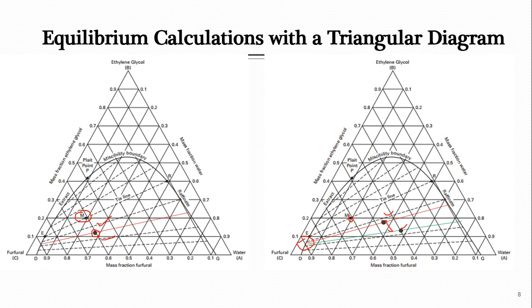So there will be very small difference in the composition, but on the raffinate side definitely there is a difference. You see here that by changing the position of this mixture point, the raffinate composition is changing from here to this, so there will be a difference in the composition. Due to this it is important to draw the line carefully so that you get close to the exact composition which you were looking for.